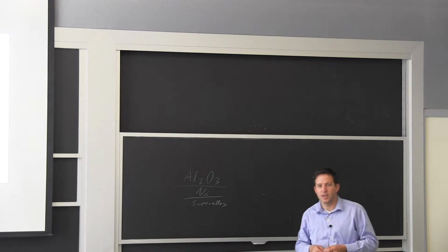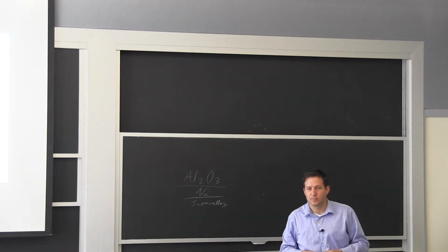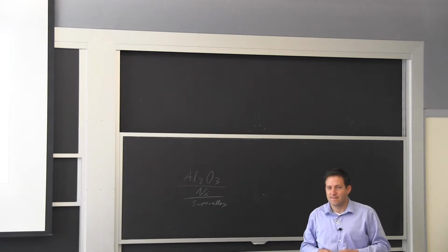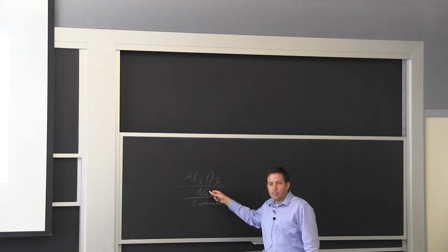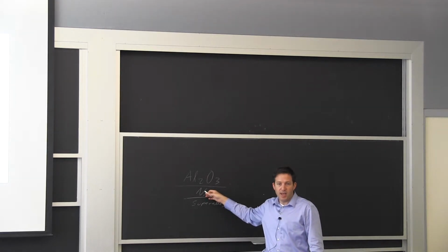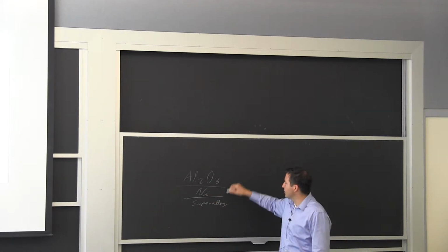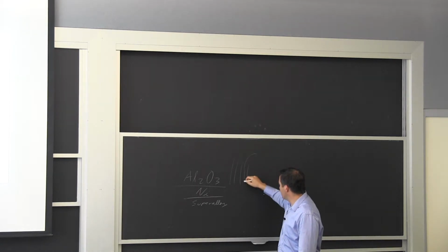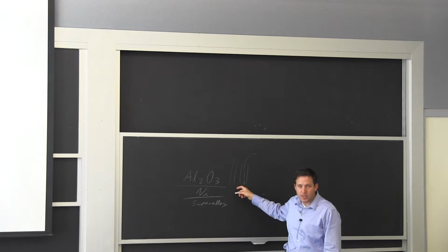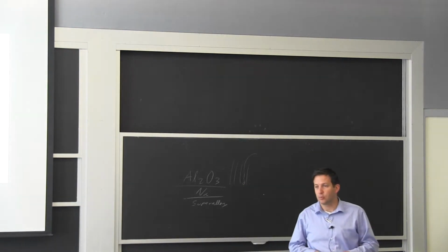Very good question. Yes? It doesn't seem to be a very oxidation resistant layer though, right? You're not really sealing the substrate. That's right, and that's why the bond layer, depending on how it's made, a lot of times is the ultimate barrier against oxidation. So if I have a little columnar structure made by chemical vapor deposition, there will be some gas penetrating all the way to the interface, and that's where you need the protection. Absolutely, good point.